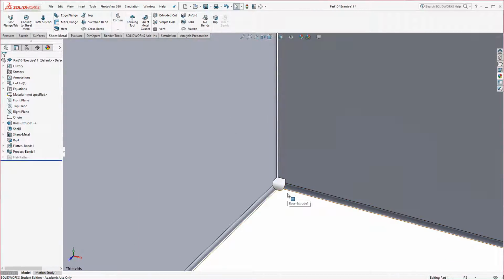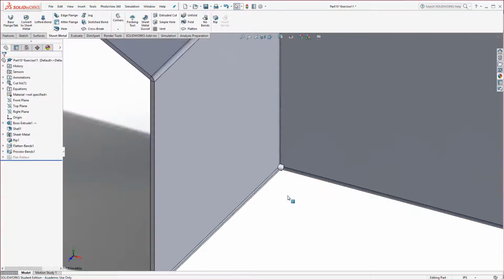freely. The reason the relief cuts are there, if you're not familiar with sheet metal, is essentially if you've ever wrapped a Christmas gift or a gift to someone for a holiday or whatever it might be. When you wrap those corners, you'll see that they bend and they kind of get these like little ripples in the corners. Same thing could happen with sheet metal, and so you put a little cut in the corner and that prevents that from happening to some degree.